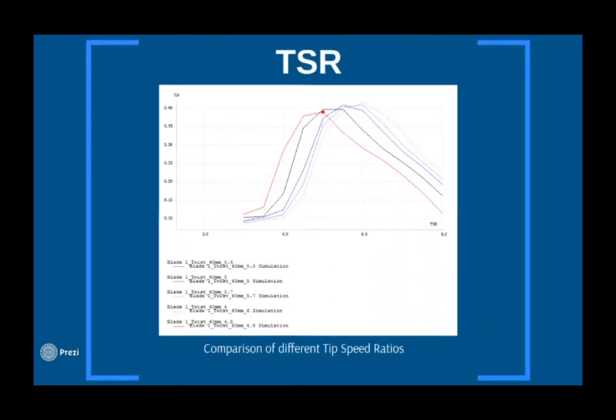TSR was initially estimated to be 4.2 based on existing literature for small turbines. The chord lengths were then calculated at each interval using Schmitz's equation and entered into Q-blade together with the twist and airfoil types. We then ran simulations on Q-blade to obtain the CP and estimated power output for each case. The chord lengths were then recalculated for different TSRs and used to predict the optimum TSR, which would yield the highest power output for our blade.